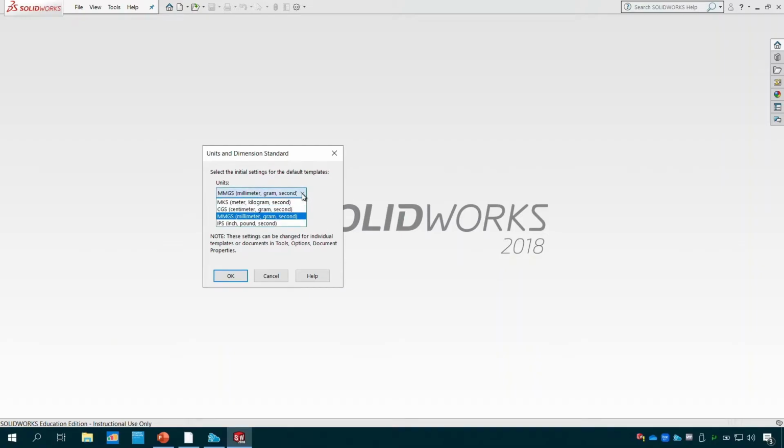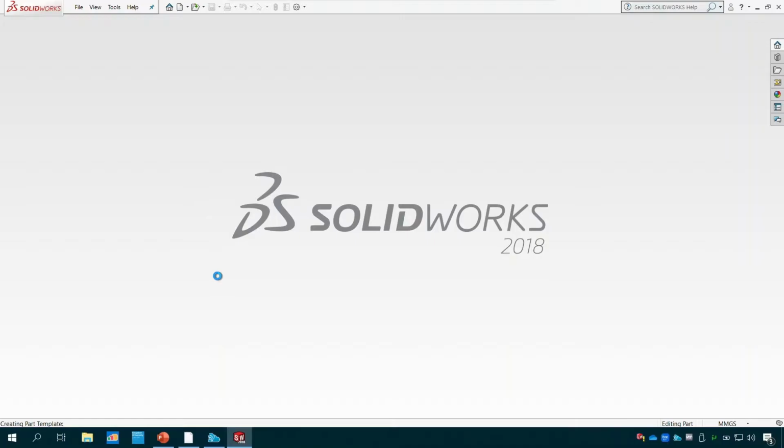Also, you would be able to identify which units you're going to go for, whether it's millimeter, gram, or second, which is the default for BSR, or you can use any other. I'm going to go with millimeter, gram, and second, so make sure any dimension that I refer to in the software is in millimeters. And now click on OK. So let the software initialize everything for you.